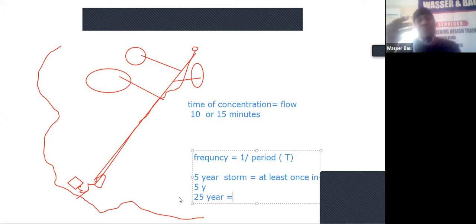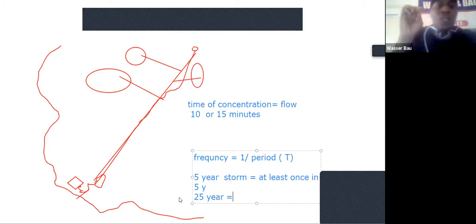When you design dams, you do your feasibility study, then you know the kind of rain that falls in that area. And then you know how many years you expect before that dam can be overtopped. If you are designing for 25 years, what you are saying is that this dam can only be overtopped once in 25 years. It might not be overtopped, but that is a design criterion.